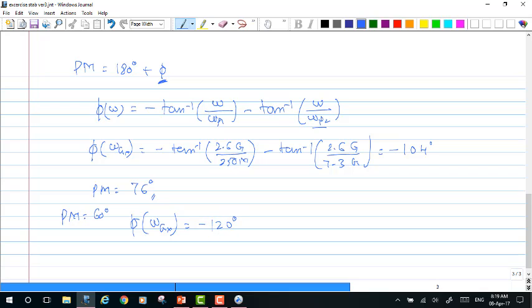What is allowed here is to change the Cy capacitance and not our Cx capacitance, which also means that the value of omega p1 will not change, because omega p1 is a frequency related to our Cx, and we are not going to modify our Cx capacitance.